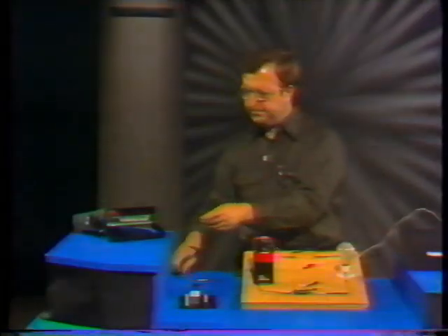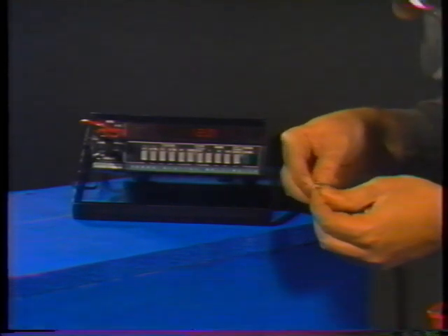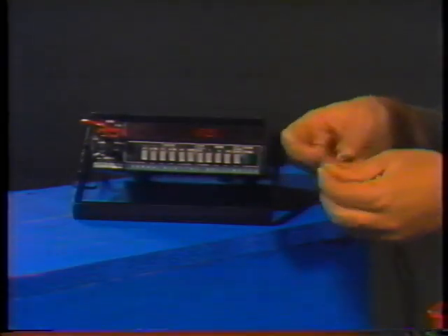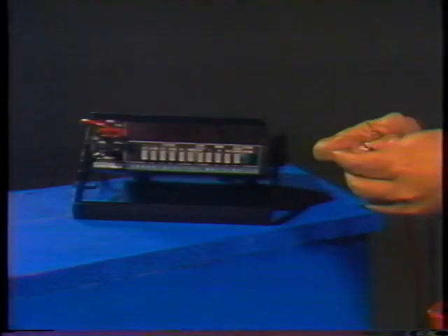Now, I will place a probe on each side. And this one reads about 12 ohms, 12. And this one, whoops, 11.9 or 12, well within the tolerance. And same for this. By the way, if you need to jot down the resistance of each of these resistors, you do it this way.